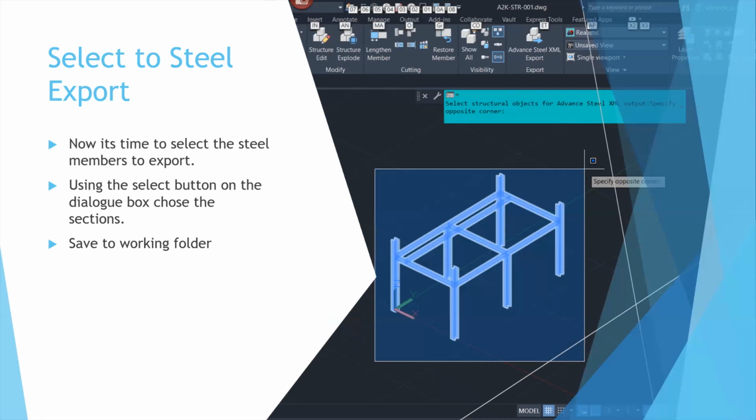So you can have a look here. Up the top, we've got select steel to export. So now it's time to select the steel members to export using the tool in the last slide. Using the select button on the dialog box, choose the sections and save it to the working folder that you've got.